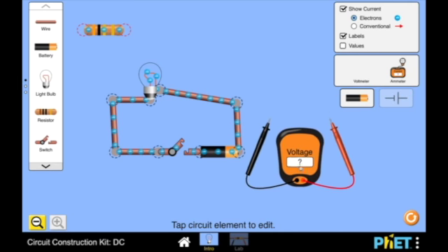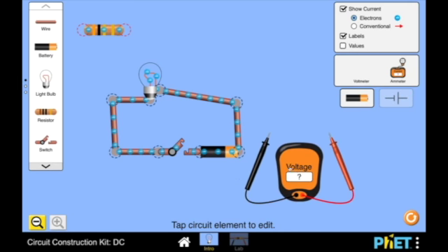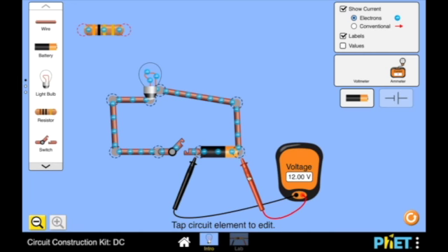Just like the multimeter that I was showing earlier, we will take the negative end and attach it to this side. In fact, if we just set it right here anywhere over the wire and the positive on the positive, you'll notice it will read our 12 volts. But if I move it over past the switch, well, now it's off.